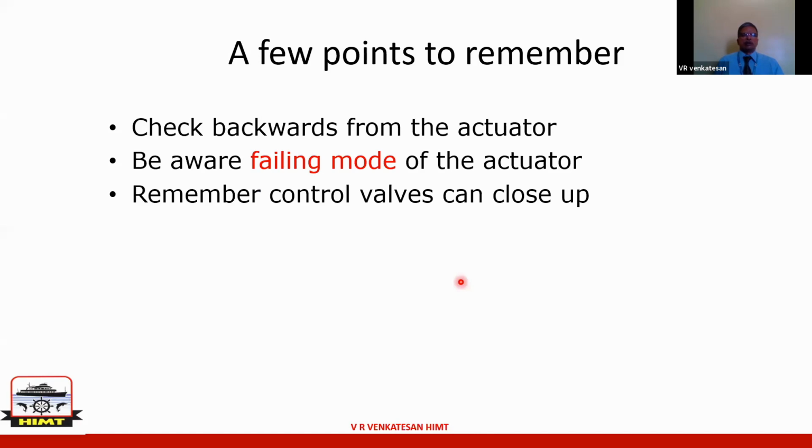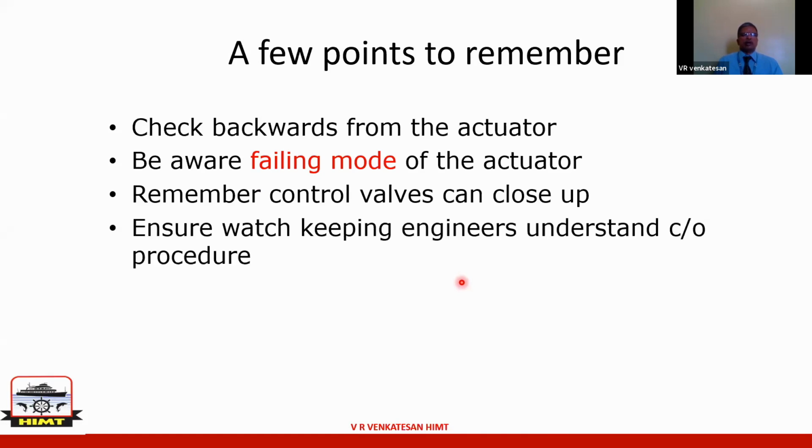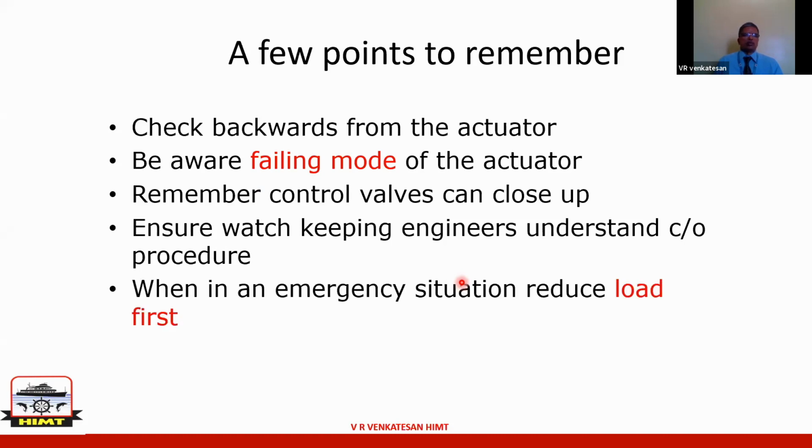Control valves can open or close while going up also. They are not like ordinary valves you see in pipelines. This you should not forget. All engineers should be aware of changeover procedures. If automation is not working and you want to go to manual mode, engineers should know how to do this changeover procedure. Whenever there is an emergency, reduce the load first. It will always give you time, rather than trying to fiddle with the controller.